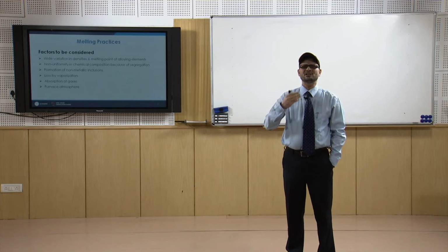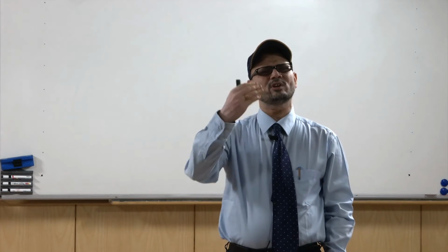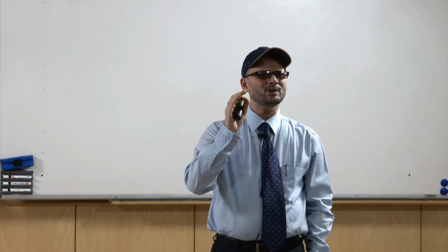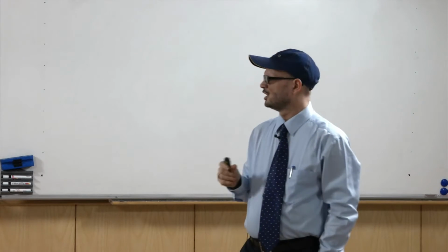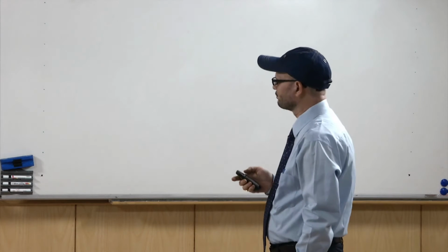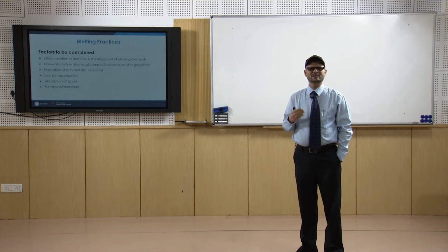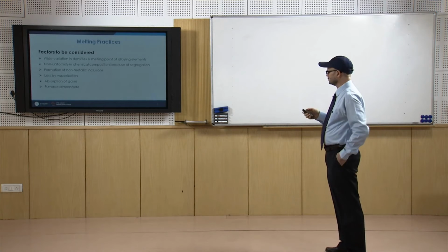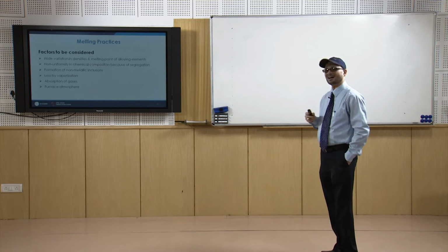If you look at the non-ferrous materials like copper or aluminium, they are mostly used for engineering applications. But pure copper or aluminium are not very much used for engineering applications because their strength is quite low. Copper is used when you need good electrical conductivity, or even aluminium for that case. But when they are alloyed with different elements, their strength increases and a lot of properties do better. So, mostly these non-ferrous materials are used in the form of alloys, though they are also cast as pure.